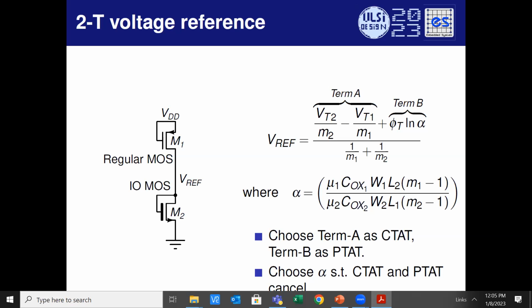So, his original plan was that we'll do per wafer characterization. We'll select one particular part from the wafer, do a factory calibration, and the same factory calibration is going to be applied to all the others. But the claim of the ISSCC paper is that this was his plan, but when it came to measurements, he found that it was not required. It behaved the same no matter what.